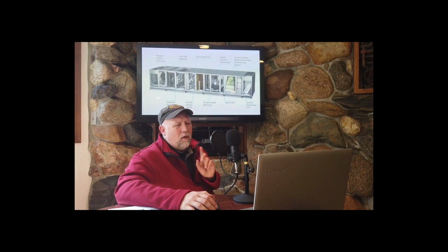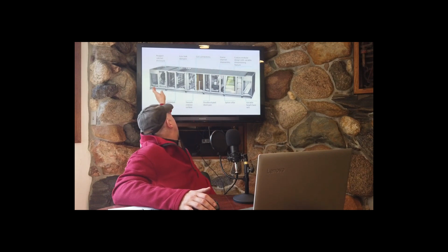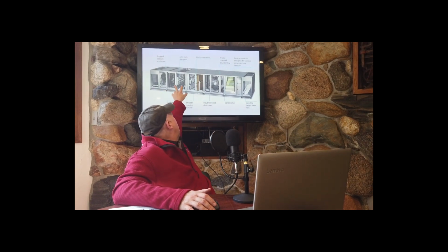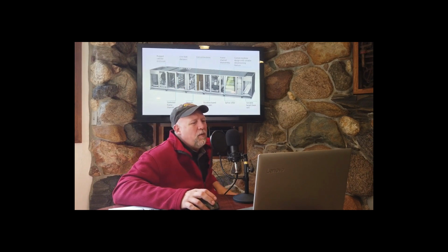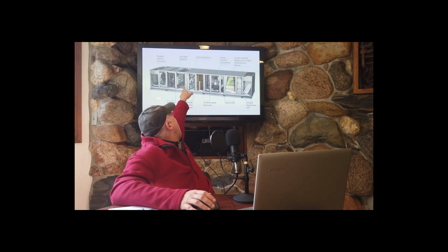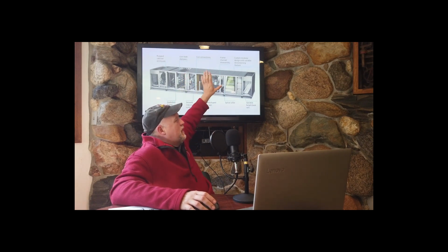Here's something a little more complicated, where we have a return fan, right? Notice dampers on the top and here. That means this is the mixing box section where we also have an economizer. We would have ductwork attaching to those dampers on the top to send some air outside and bring some inside.